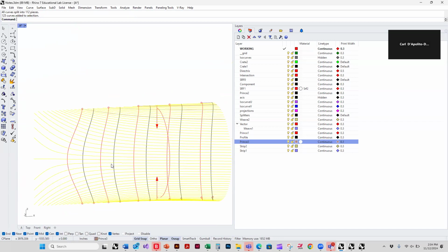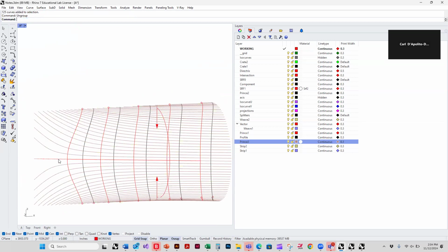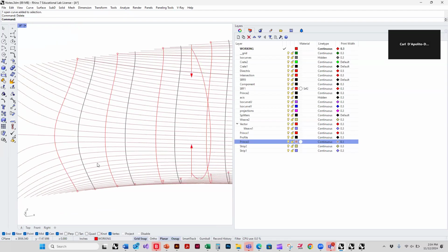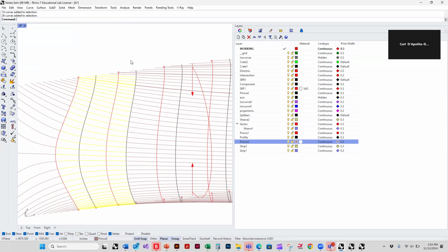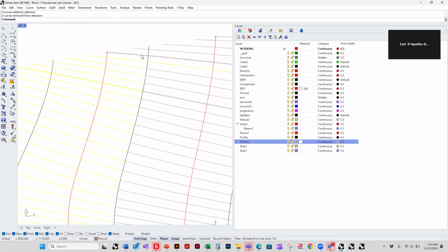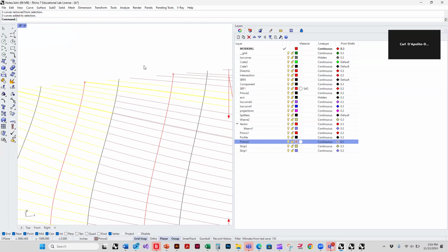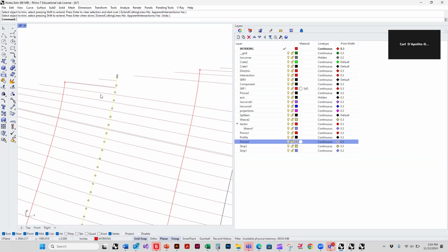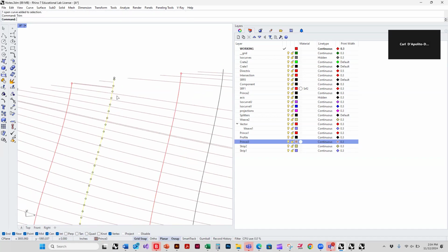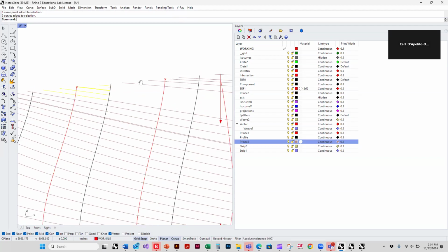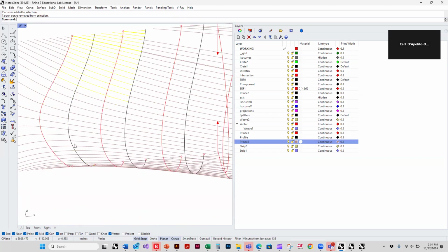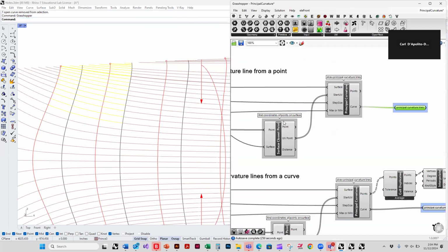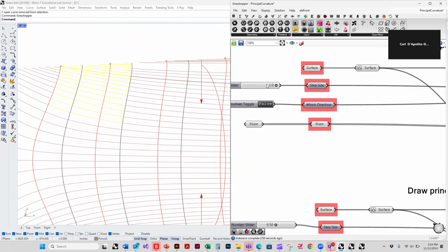Okay, so once they're split, sometimes some of you have told me it won't split. And when it doesn't split, so all of these split. Oh no, good, some of them didn't. Okay, so these, when they don't split, you can trim using this line here. And that's just a kind of loose, bad approximation. The reason it's not working is because of the tolerance here. The step size is not totally on the surface. It's moving along the surface in a series.